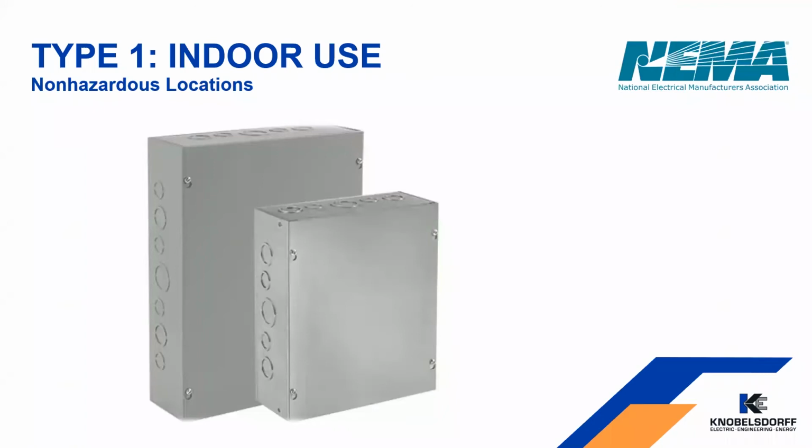No reason we can't use cable tray and cable tray cable in both a Class 2 Div 1 or Class 2 Div 2 location. Just have to make sure you're using the right type of cable. There's just regular PLTC cable, and then there's also an armored TECK cable that we can use in the Class 2 Div 1 locations, and then it also has a special fitting that goes with it.